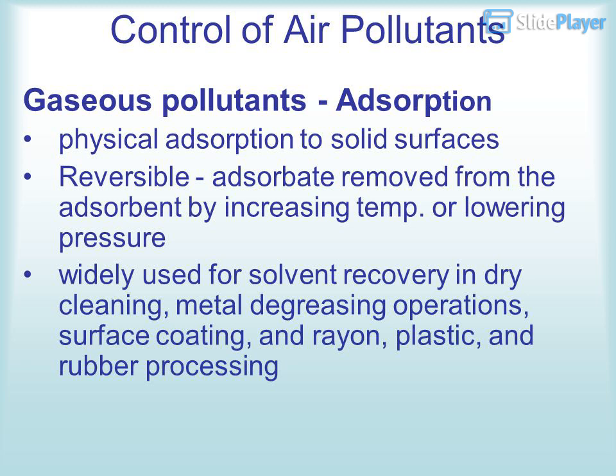Control of air pollutants. Gaseous pollutants, adsorption. Physical adsorption to solid surfaces. Reversible, with the adsorbate removed from the adsorbent by increasing temperature or lowering pressure. Widely used for solvent recovery and dry cleaning, metal degreasing operations, surface coating, and rayon, plastic, and rubber processing.